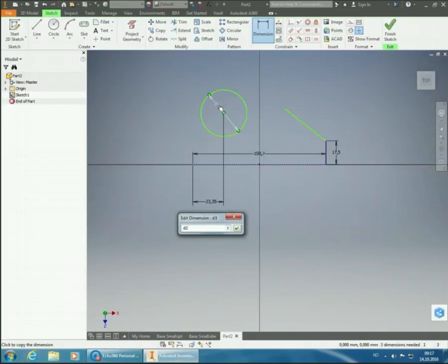And that means that when we fill in D2 here, Inventor knows that right now that is 35 millimeters. If I later on change the diameter here to 40 millimeters, then it's going to change to 40 millimeters in here also. But this is the diameter, and we need the radius here. And since the radius is half the diameter, we can put in divide by 2.